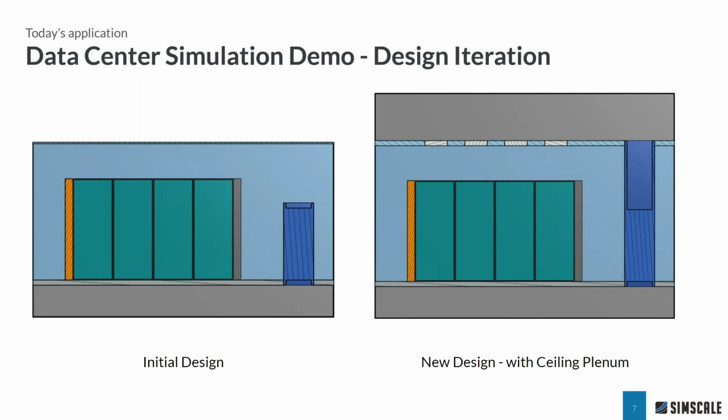On the left, we have the initial design. What this means is we've got a room return. So the air goes through the racks, becomes hot in the hot aisle, and then room returns. Now, what's interesting on the left is there's not a lot of space above the racks. Pretty tight room. If you are going to go with a room return, it's always great to have tall ceilings, but a lot of times that's just not a reality.